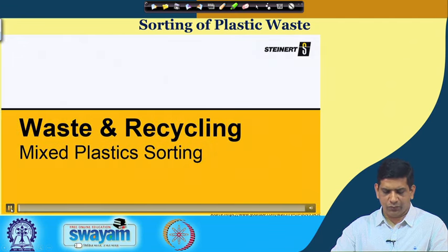Now, after that you have an eddy current separator. What the eddy current separator does is remove aluminum cans. As you can see, things get blown away and it separates aluminum parts. Anything with aluminum gets blown away in this eddy current separator, so aluminum is taken out, and that can go as aluminum waste. The rest is what remains after removing iron and aluminum.